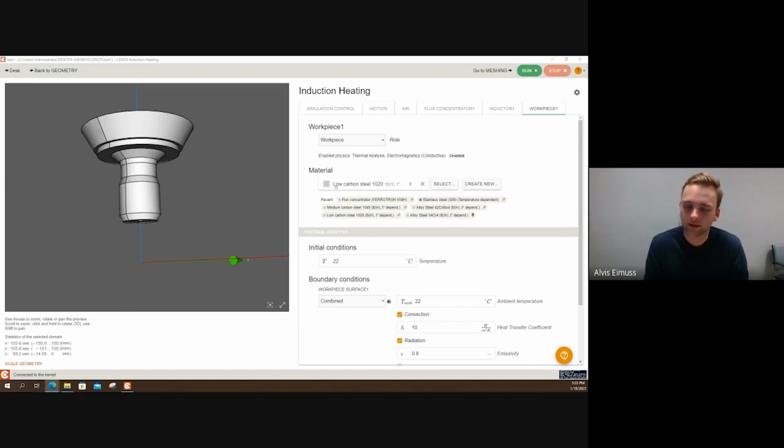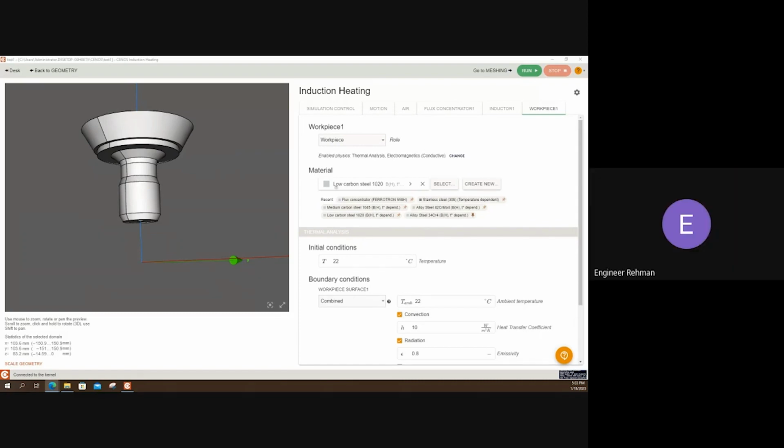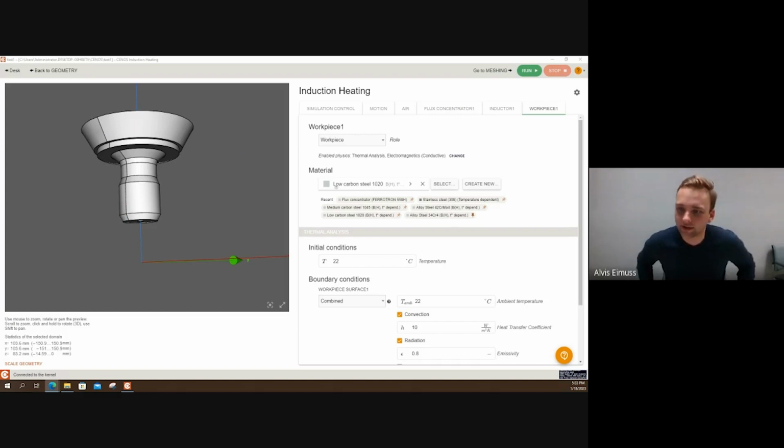Basically, if you go into Salome, this is one of the reasons why we moved to our own meshing, that you need to be very careful about what you do and what you export. Because at the point of export from Salome back to CENOS, there is a list of phases and volumes that you need to check or leave unchecked in order to correctly export the mesh back to CENOS. And if by any chance or a simple misclick, you either do not select everything that you needed or select something too much, then this kind of problem can occur.